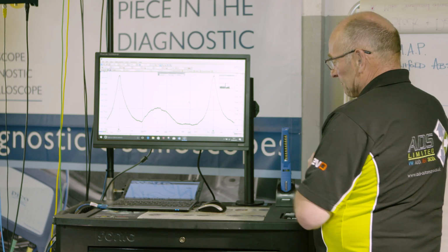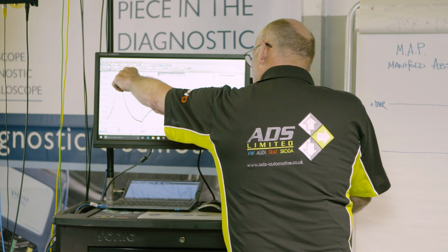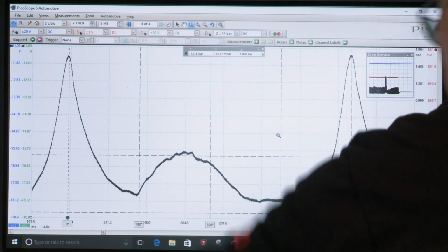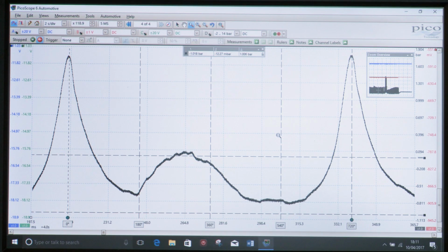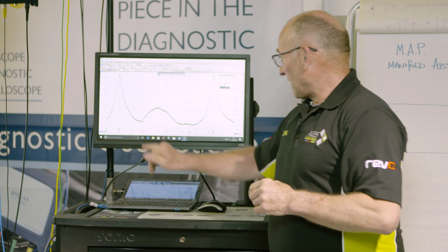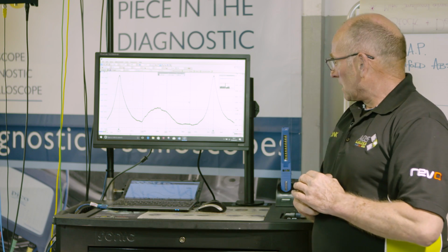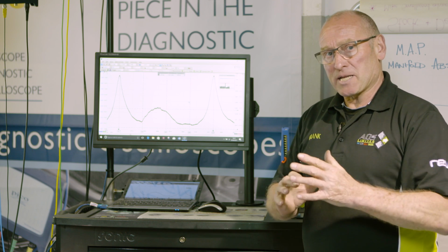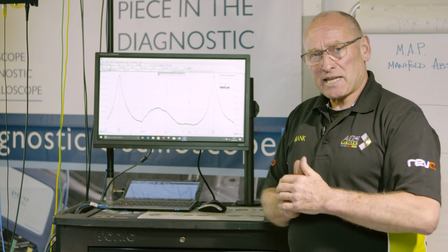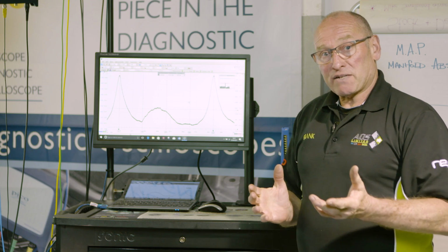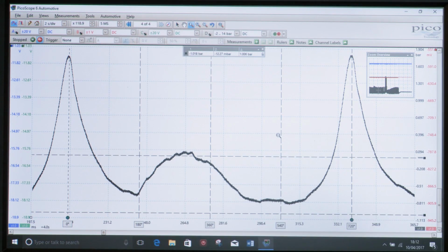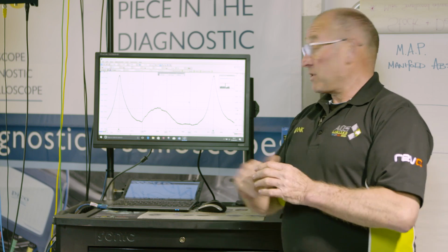Well, I have an interesting question. If this is the power stroke, and it definitely is, why is the pressure dropped below that of atmosphere? Now, it's called an expansion void, and it's a void established during the expansion that takes place in the cylinder. Now, the principles of this are laid down by Boyle's law, and it's the properties of gases under pressure. Now, in our case, what we have is a sealed chamber, and I hope that the valves are closed.